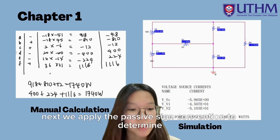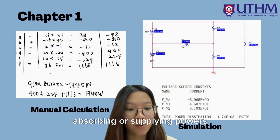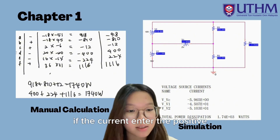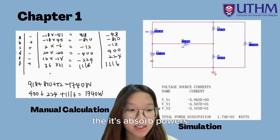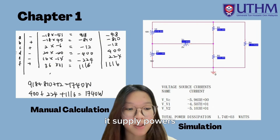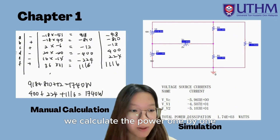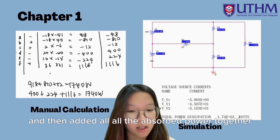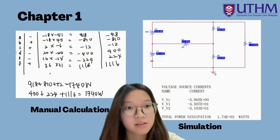Next, we apply the passive sign convention to determine whether each element is absorbing or supplying power. If the current enters the positive terminal of an element, it absorbs power. If the current enters the negative terminal, it supplies power. After identifying each element, we calculate the power one by one and then add all the absorbed power together and all the supplied power together separately.